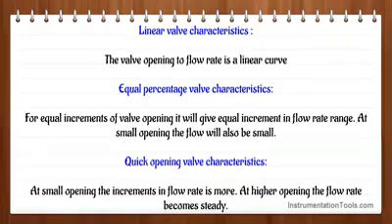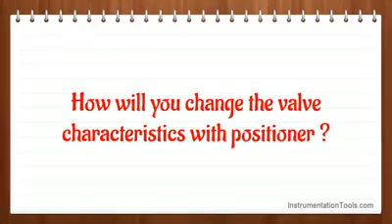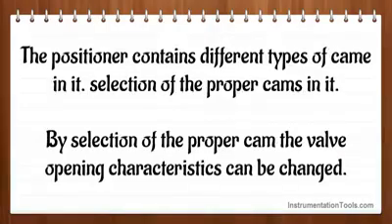At higher opening the flow rate becomes steady. How will you change the valve characteristics with positioner? The positioner contains different types of cam in it. By selection of the proper cam the valve opening characteristics can be changed.